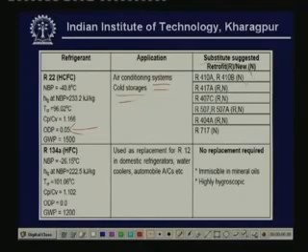Again, these are the major substitutes. You can see that according to our numbering system, all these 410, 410A, 410B, 417, etc. are zeotropic refrigerant mixtures, whereas 507, 507A are azeotropic refrigerants. And you can also replace R22 by ammonia, that is R717, but not as a retrofit, only as a new system. Another important refrigerant is R134A.